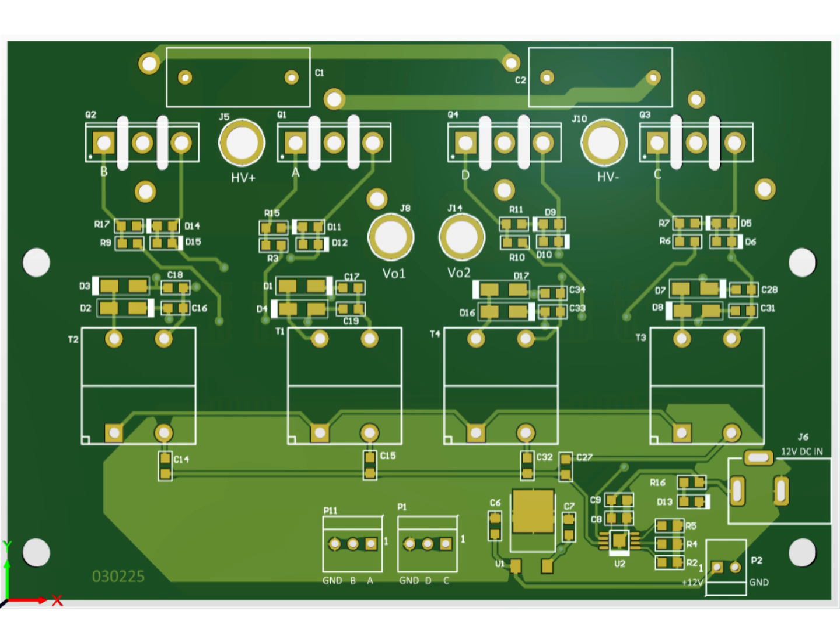The DC bus input connectors, labeled HV+ and HV-, are positioned close to the corresponding half bridges. This helps keep the high-current DC bus paths short and wide, reducing parasitic inductance and voltage overshoot during switching. The output terminals, VO1 and VO2, are taken from the midpoints of the two half bridges and are centrally located to maintain symmetry between the left and right legs of the H-bridge.